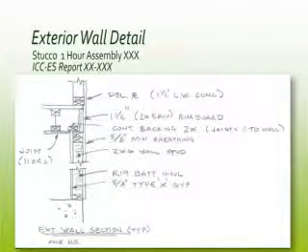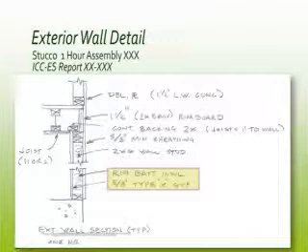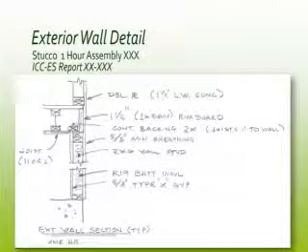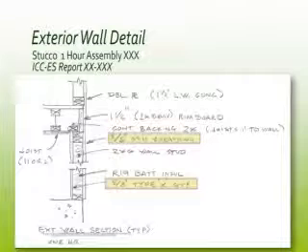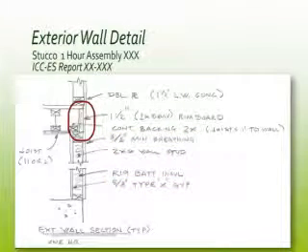The exterior wall, again, is pretty straightforward. The lower section of the wall is going to be stuccoed, 5/8 type X on the inside, bad insulation for the sound, and conventional insulation for that matter too. But if you look at the interface, now remember we had to have fire from the outside and the inside, right? So probably not too terribly worried about fire on the inside because you've got a 1 hour assembly at the bottom by 5/8 here, 5/8 here. On the upper side you've got your deck and you've got 5/8 up to that, so that's all good and happy.